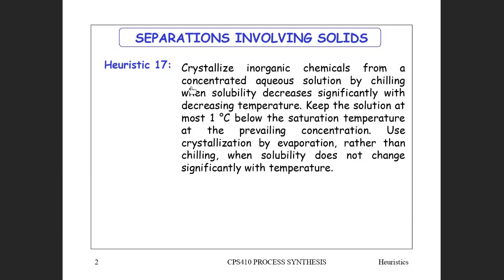Crystallize. Okay. So we're going back to the missing heuristic. Crystallize inorganic chemicals from a concentrated aqueous solution by chilling when solubility decreases significantly with decreasing temperature. So now we're talking inorganic chemicals. Keep the solution at most 1 degree C below the saturation temperature at the prevailing concentration. Okay, now this is,